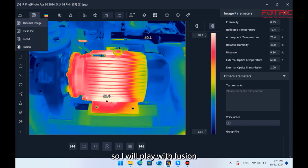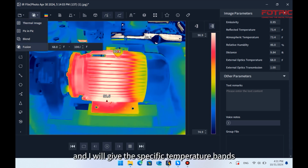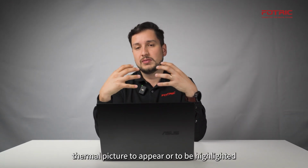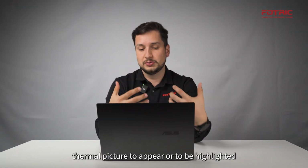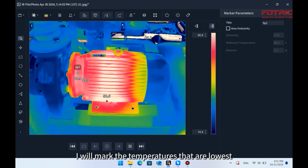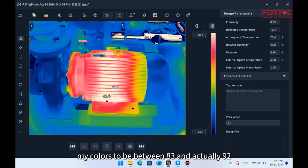So I will play with Fusion, and I will give the specific temperature bands where I want the thermal picture to appear or to be highlighted. So before, I will just do a little exercise. I will mark the temperatures that are lowest in the motor. So this is 83, and then the highest is 89. So I know that I want my colors to be between 83 and actually 92.